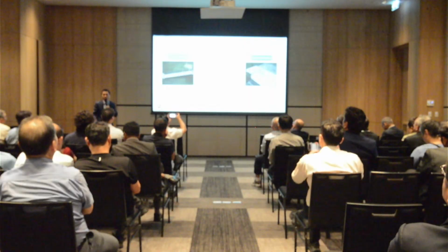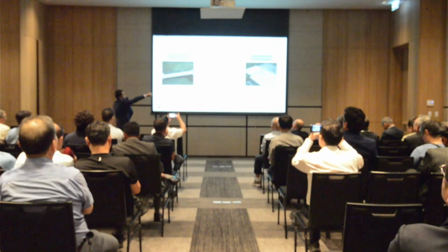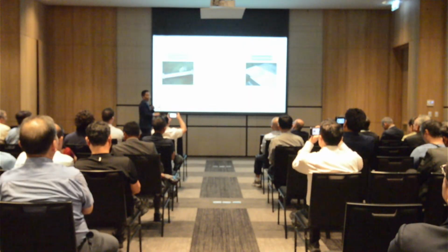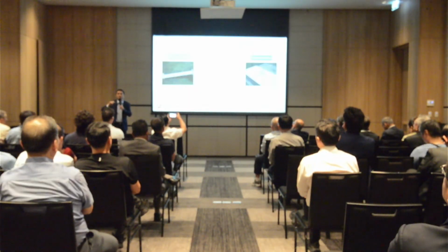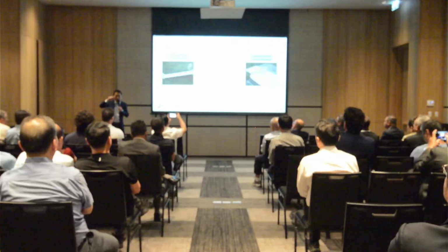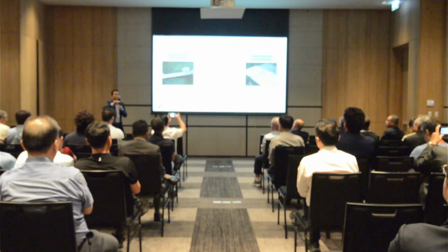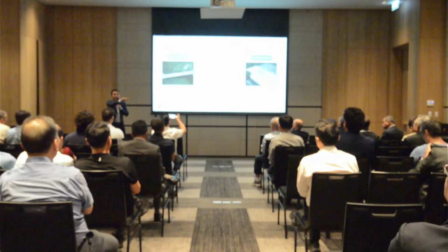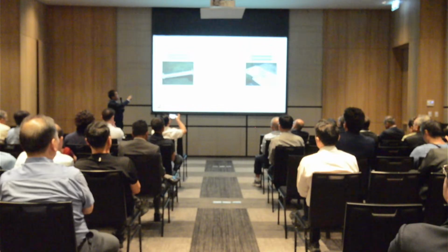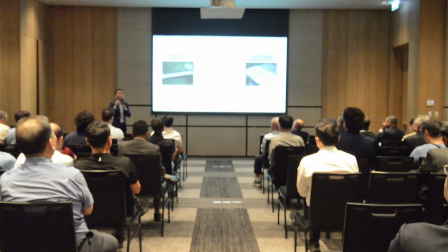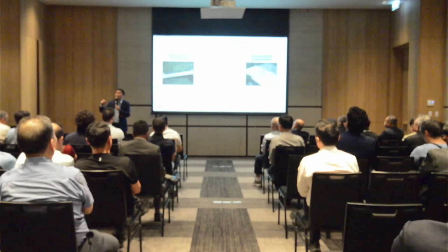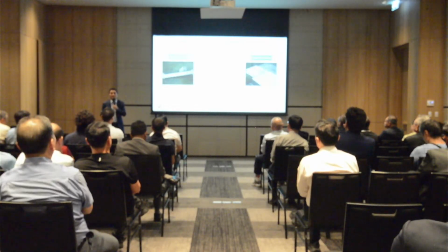It's like traditional semi-solid. It's a very high solid fraction. This one is a lower solid fraction. But all this process is below the liquidus, because below the liquidus you get equilibrium. This is equilibrium conditions. The solid fraction is fixed, the viscosity is fixed, everything is fixed. That's why this also limits the application of the semi-solid technology.